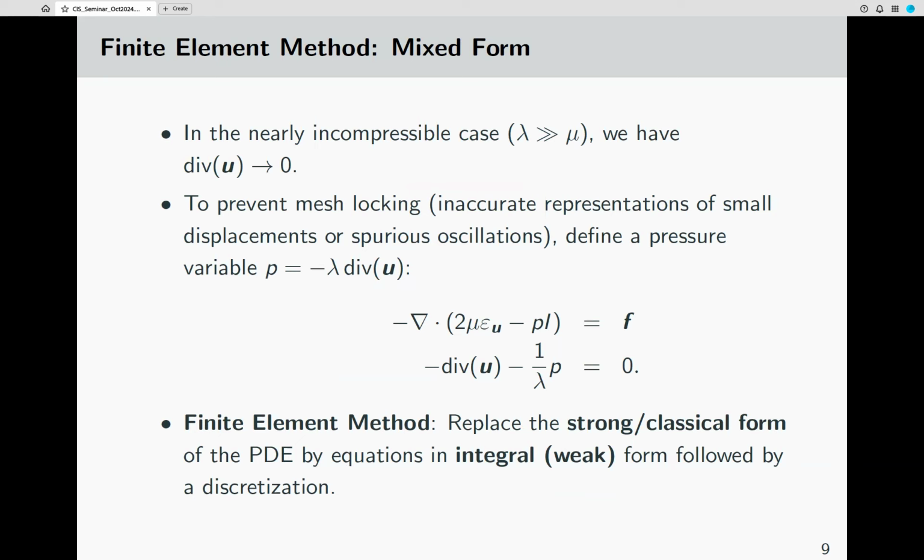Okay, so here are just a few things. Again, nothing super complicated, because we are talking about the nearly incompressible case. You saw how lambda is going to be extremely large. So the scale between this lambda parameter and the mu parameter is going to be very, very different. For example, in our case, we take a really large value, lambda is like 10 to the 6. And mu, depending on the situation, could be something like 4, 5, 6. That's the range we are talking about.